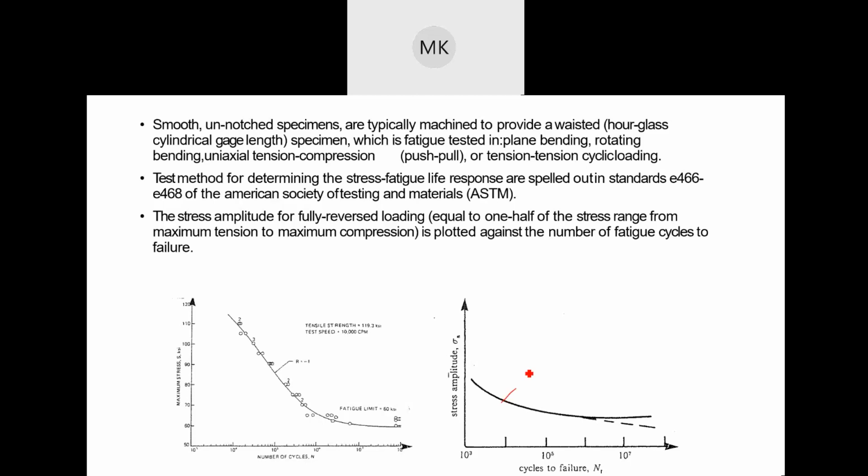So I would start something at 80, 90%, and if it's less than 10 power 4 cycles, because for high cycle fatigue I need stuff from 10 power 4 and above. So if 90% is at 8,000 cycles, which is less than 10,000, I would do another one at 80%, and then 70%, then 60, and then 50. So I would know that 50 and 60 might both be 10 million cycles. So I know that anything below 60%, it is going to have unlimited life in the material.